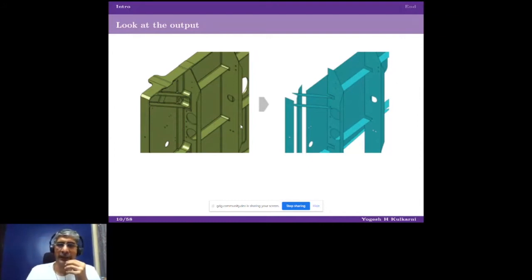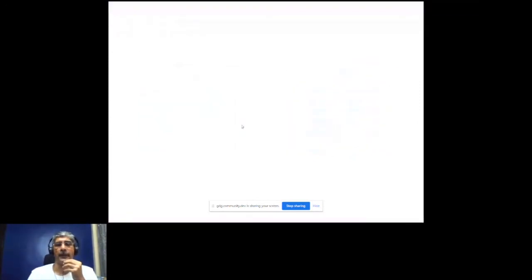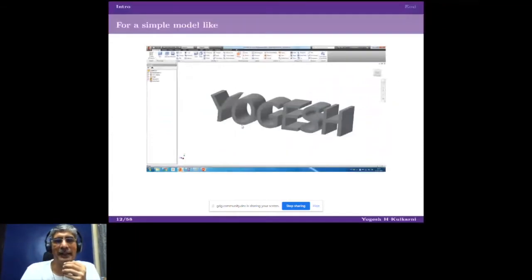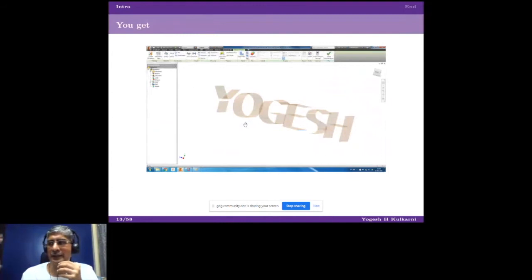How to create a shape. Even if you don't follow this domain, just try to understand as much as you can. The real problem is a little later. Okay, I'm talking about how to simplify a problem. So we cannot tolerate gaps. So if you model a 3D shape like this, what would be its mid-surface? Can you imagine? It would be a surface shape in the middle. And ideally, it should look like this. But currently, as you can see, there are gaps. I want a shape like this, but without gaps. So this is what the current, almost latest, software does too. Then what do people do? People go on putting in surfaces and closing the gaps. So this is a manual effort which we want to avoid. If this transformation from solid to surface were very good, we wouldn't have to do manual corrections.